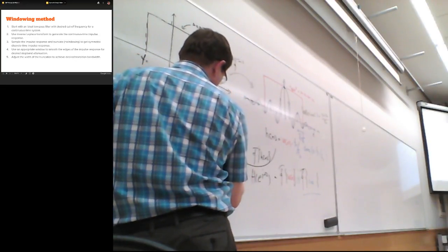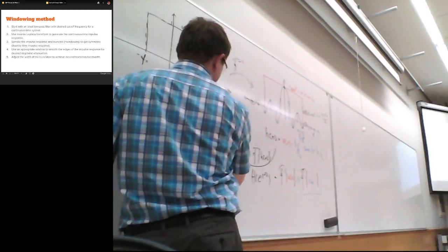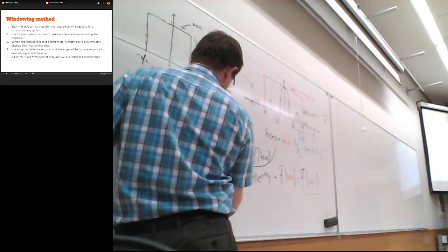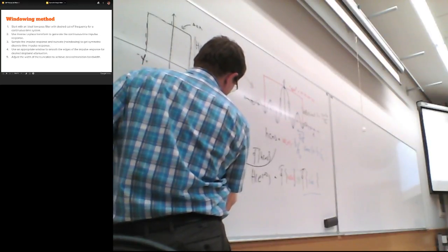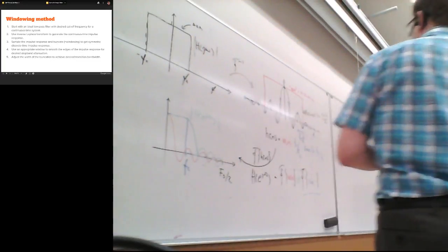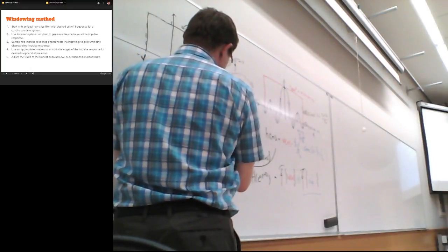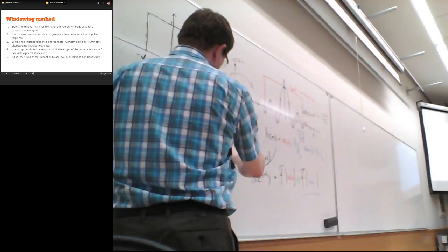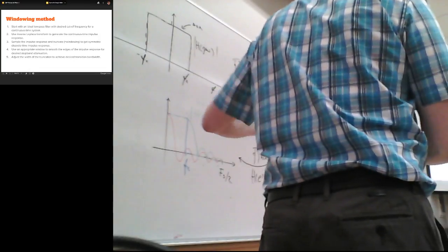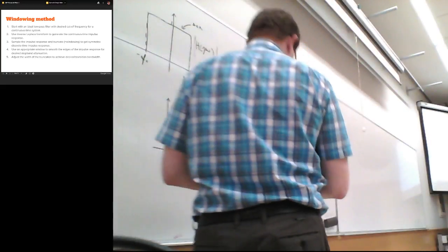Although, okay, I'll just mark this one as, if this one is the amplitude response of H(e^jω), then actually this is the absolute value. Okay, so having the box shape window will make the transition bandwidth wider, and also it does not get all the attenuation because the sinc has every single frequency available from here to beyond.